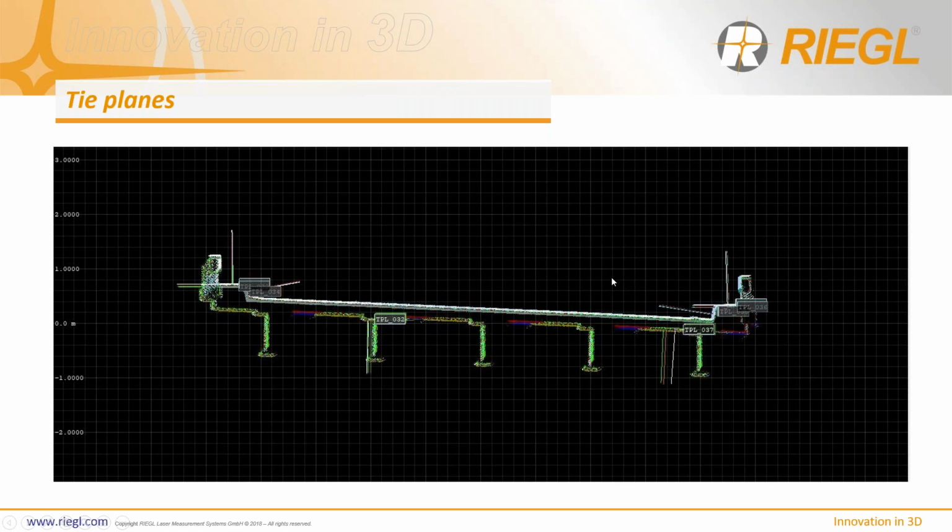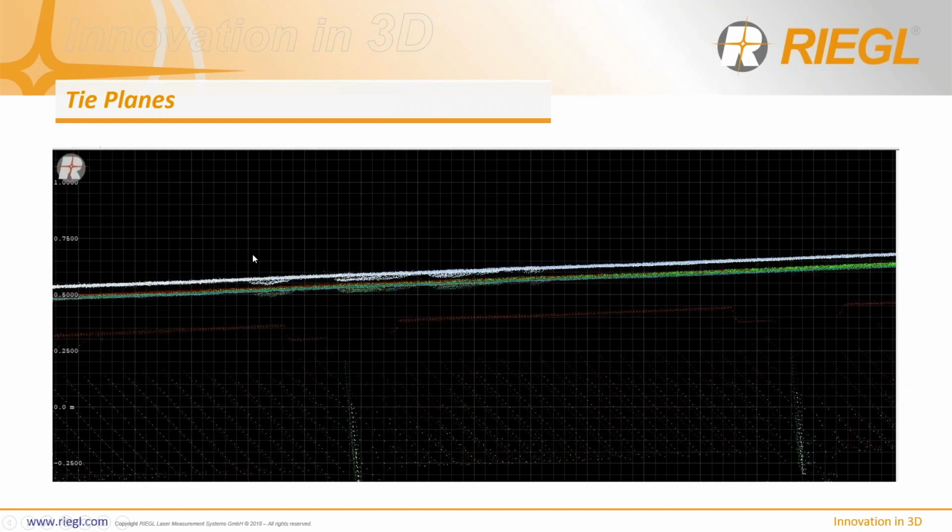You notice I'm not selecting wide surfaces along the road surface. There's a couple reasons for that. One is that there are sometimes potholes in the road, and if you select the big surface there, it's really tricky. You're asking it to match everything together spot on, when in fact it doesn't match perfectly. There's a slight angle there, so it all depends on how you're looking at it.